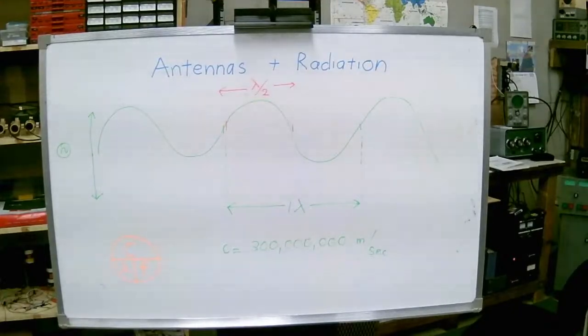That last little device we used. Yeah, because we want to be able to have DC coupled all the way through. And so we want the midpoint to be a ground potential there. If we don't use a bipolar supply, then we have to use coupling capacitors so we can have the voltage swing plus and minus.